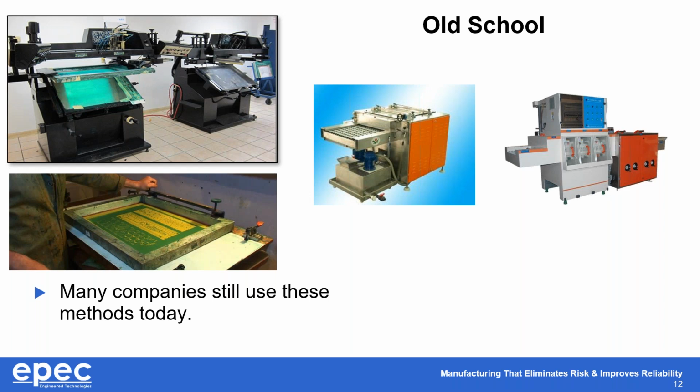It's not that high a pressure. There's no vacuum pulling it through the hole. So there was a whole bunch of challenges with that. And this equipment, believe it or not, is still in use today for old school factories who are trying to fill vias with it. The other thing that you'll see is the picture right next to this with the blue background, a pumice scrubber, and that's really used to prepare the surface when you're adding something like a solder mask to it.